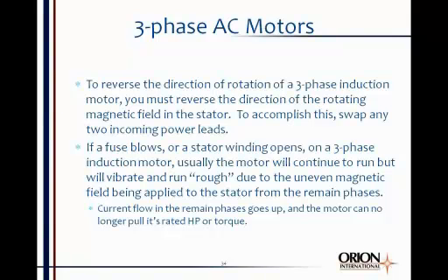Now, if a motor is operating along and goes into some kind of a condition where a winding burns up or a fuse blows, or anything happens where one of the phases is lost, usually the motor will continue to run, but it's going to vibrate and run rough. This is called single phasing of the motor. The roughness is due to the uneven magnetic field being applied to the stator. It doesn't have 3 phases applying it, it just has 2 phases and then an opening. So it's not an even magnetic field being applied.